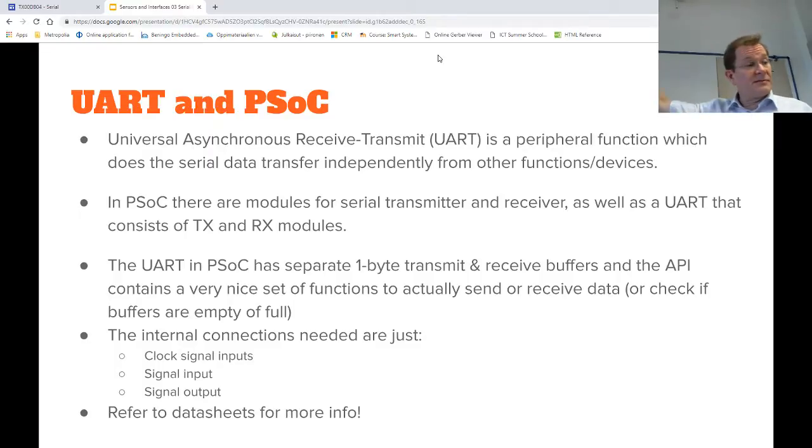You probably have played with that in some other course. That's the most common way of starting a communication between devices. Simple serial line connection: you just set the bit rate, parity, stop bits, and start transmitting. That's the normal way of doing a wired transmission.